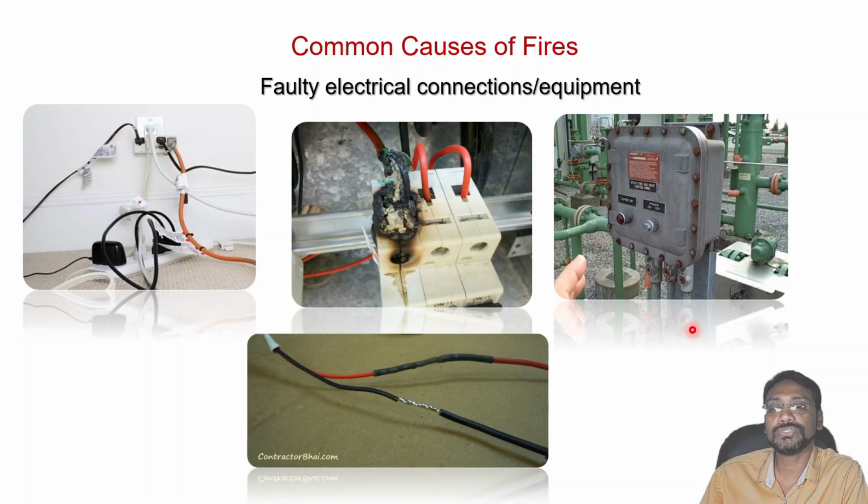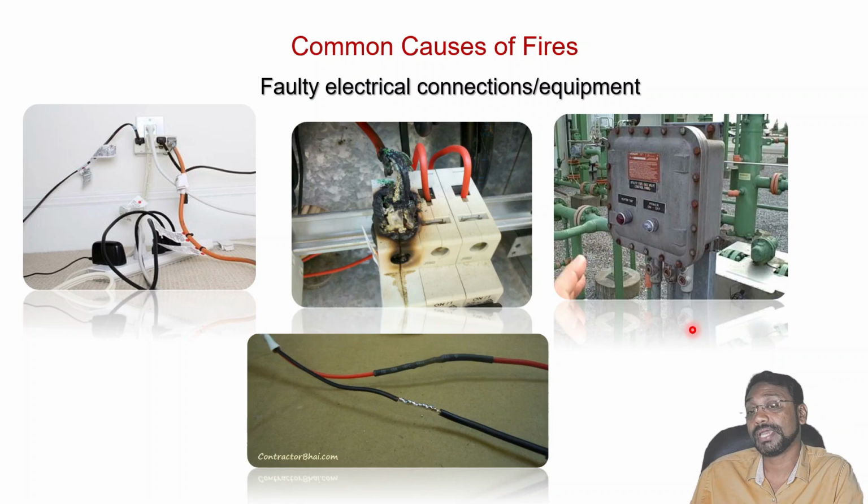Then common causes of electrical fire: faulty electrical connection, loose connection, overload, junction boxes, extension cords, low quality extension cords. All this can create a short circuit, and maybe Christmas trees. I have seen that in Christmas time, people use Christmas trees with an extension cord. They purchase a low quality extension cord. In the night it will be glowing. Sometimes there will be a short circuit.